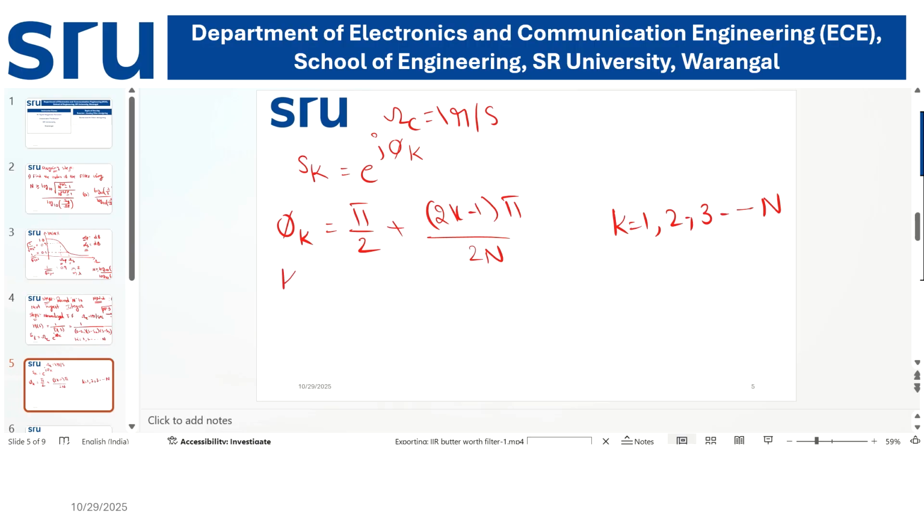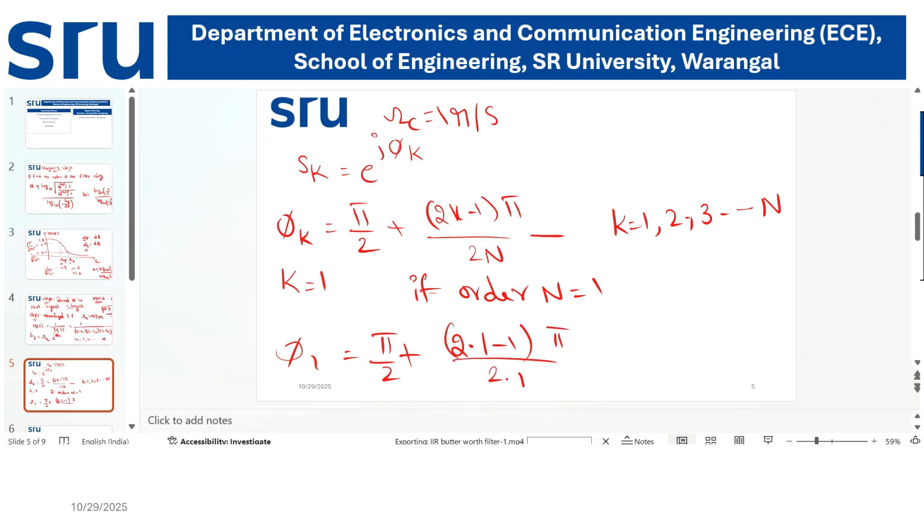Suppose the order of the filter is equal to 1, which you get from steps 1 and 2. Then the k value is equal to 1. If I substitute in the equation, phi 1 is equal to pi by 2 plus (2 into 1 minus 1) divided by (pi by 2 into 1). Therefore, I get pi by 2 plus pi by 2. What is the phase here? Phase is equal to pi.